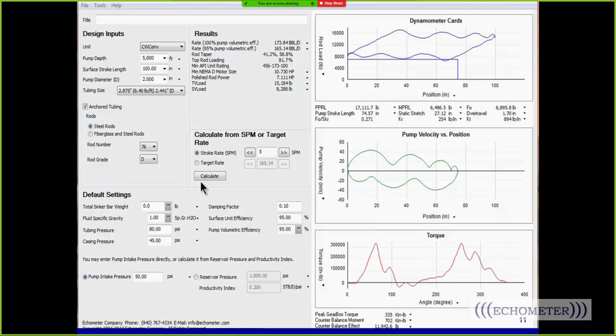But if you set the tubing anchor below a formation that produces solids, and the solids fall out on the anchor and cause the anchor to stick or block it, then you set the anchor too deep. And so some companies won't set the anchor below their producing formation because they don't want to get solids on the anchor. But some formations don't produce any solids. If you have a vertical well, then it's best to put the anchor deep because you want to set your pump in the rat hole if one's present.